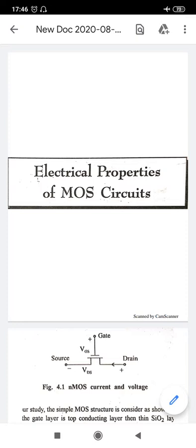the working is controlled by the capacitively coupled electric field acting perpendicular to the semiconductor surface. The MOSFET is also named the insulated gate FET, because the physical structure of this device emphasizes the fact that the gate electrode is electrically insulated from the device body by the oxide layer. Because of this high insulation, the IGFET has a high input impedance, because this eliminates any possibility of feedback from the output to the input.